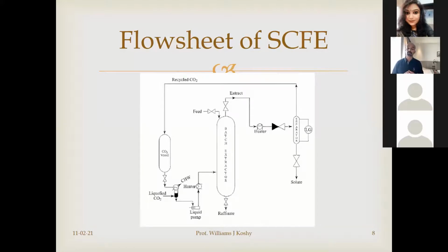Initially, you reduce the temperature. Why? अगर शुरुआत में उसको लेके हम लोग directly, if we put it in a pump, positive displacement pump, where the pressure increases above its critical pressure, उसका temperature बढ़ेगा. और अगर उसका temperature उसके critical temperature के ऊपर चला गया, in that case, ये CO2 को फिर liquefy करना possible नहीं होगा. So that is the reason why initially we reduce the temperature.